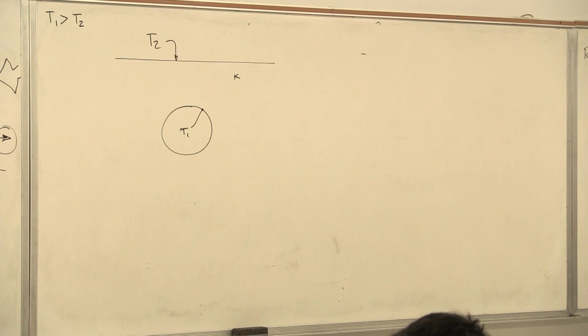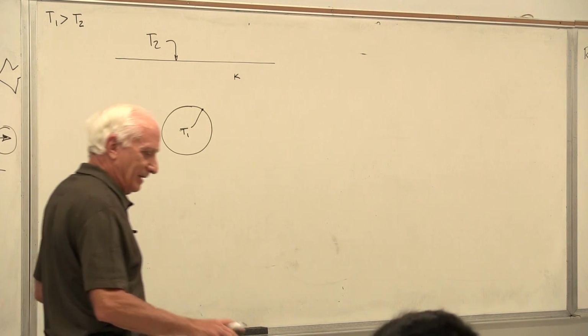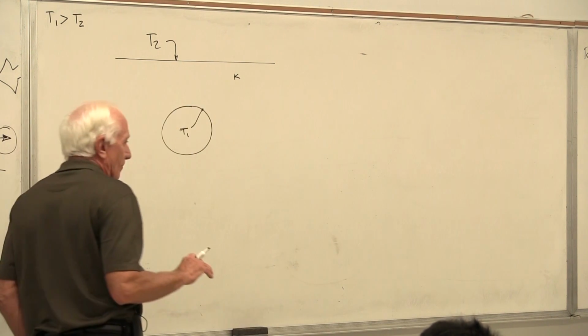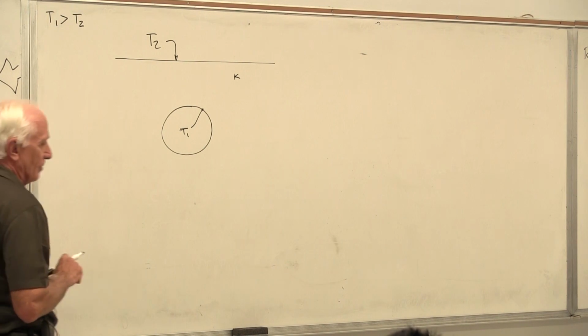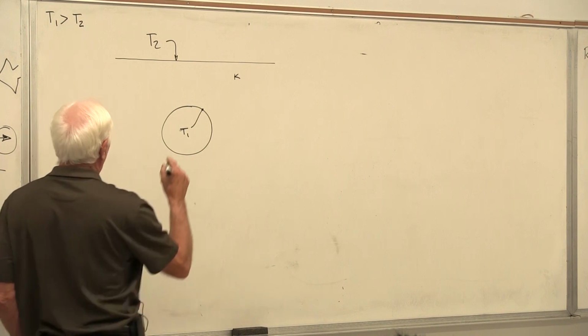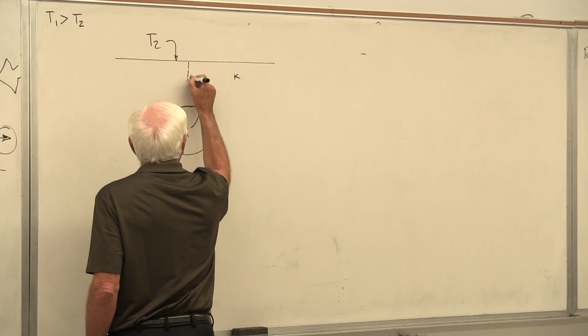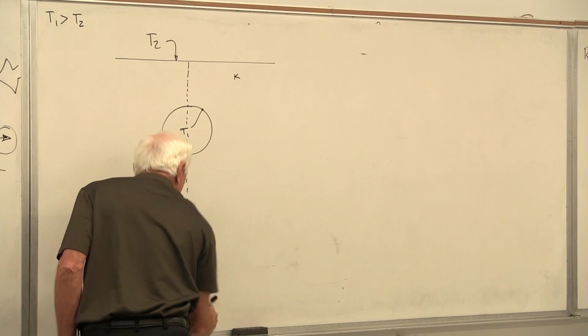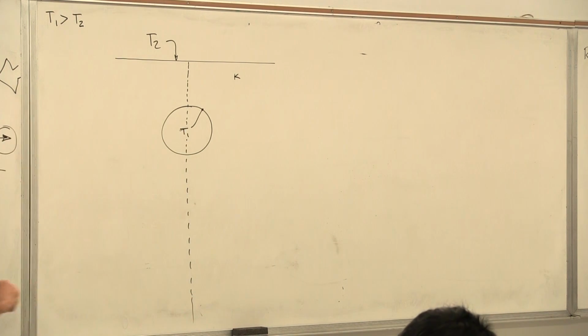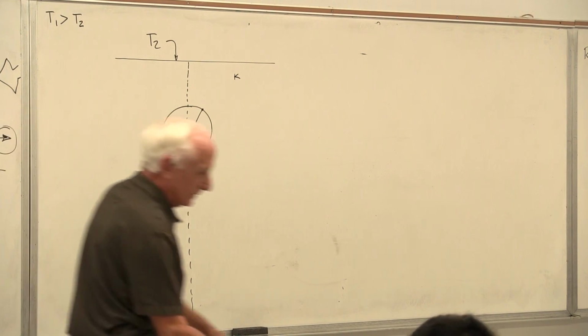You don't need to draw curvilinear squares. I'm not going to do an analysis for that. Just draw the heat flux plot. Okay. Number one rule, look for lines of both geometric and thermal symmetry. The only one we got is one that goes right through the center of the sphere. There it is, a line of symmetry. Geometric? Yes. Thermal? Yes. Okay, got it.